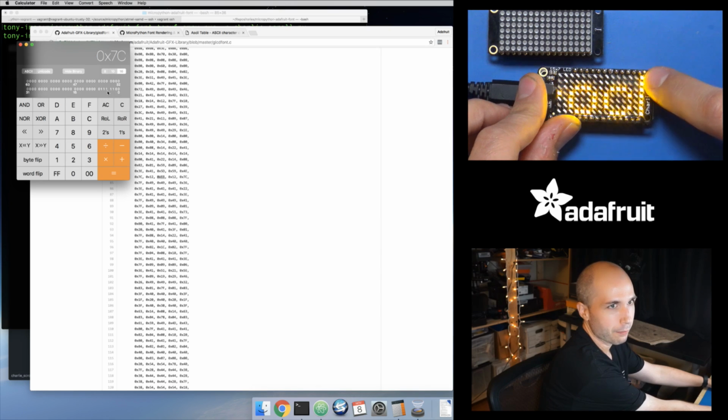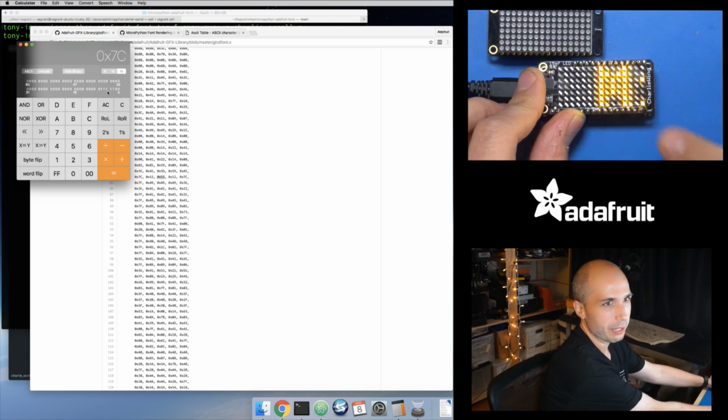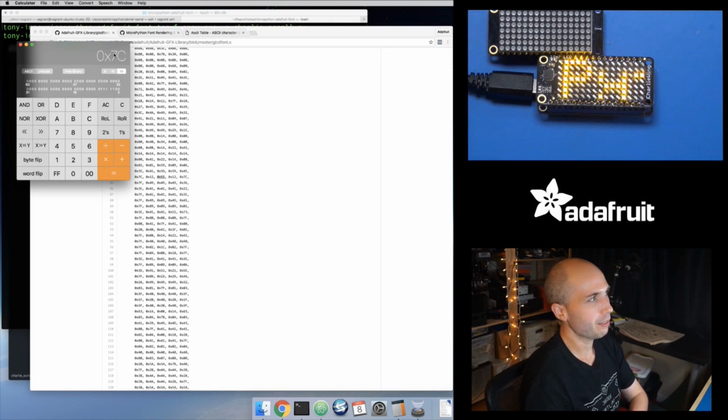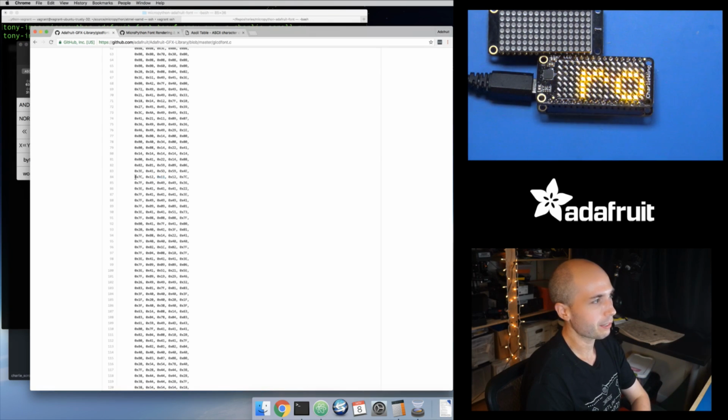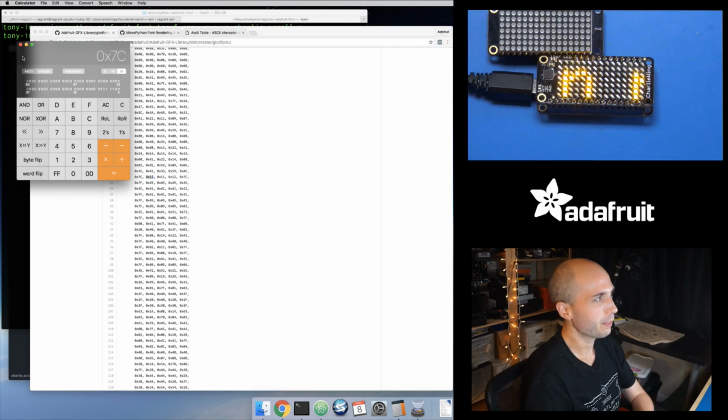So, off, on, all the way down, just following the bytes defined in that 7C character. Then for the next column, it's the character 0x12. In the hex bytes for this, it's 0, 0, 0, 1, 0, 0, 0, 1, 0. So this is maybe the inside of that A character you can see here.